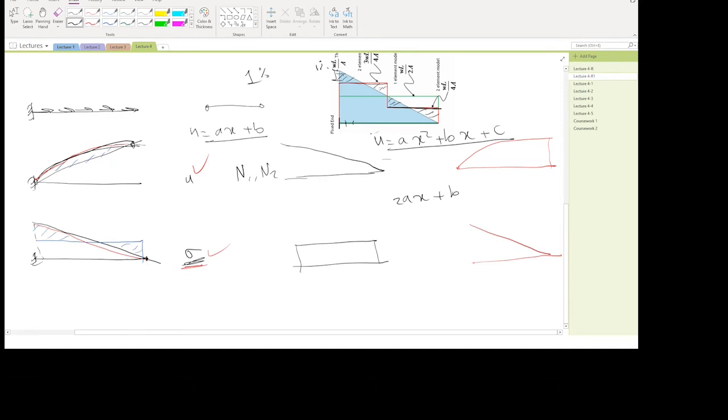See, in one element, which has this type of expression or this type of approximation, one element would be able to capture this exactly. And we are talking about zero error here. Whereas in this case, if we want to get 1% error, we're talking about 50 elements. So instead of using 50 elements, you can use one element and get the exact solution. So see how efficient that is? This is quite an efficient way to capture the solution.